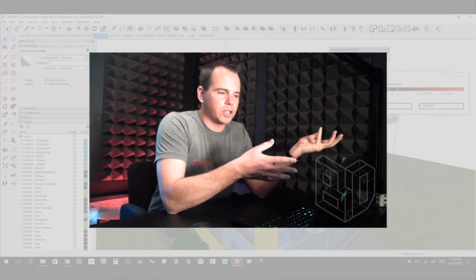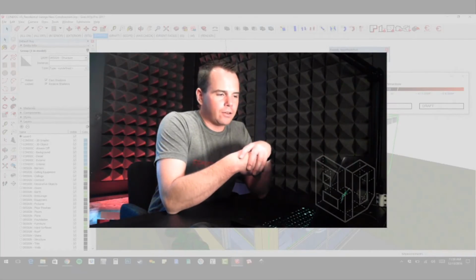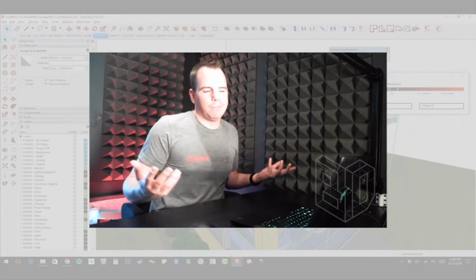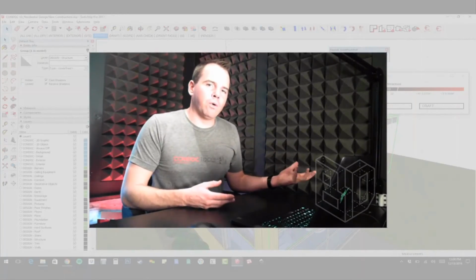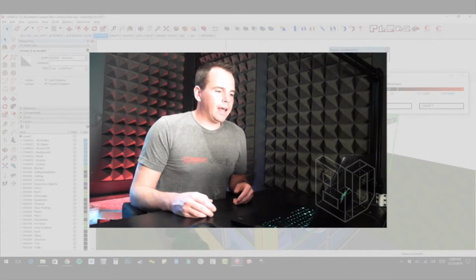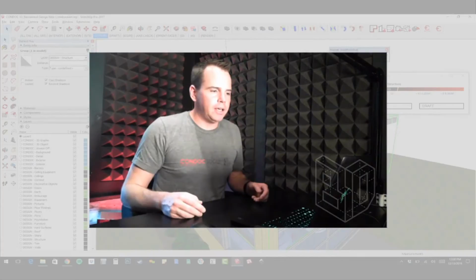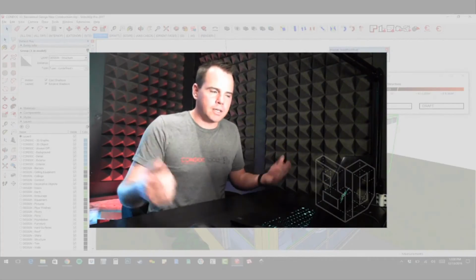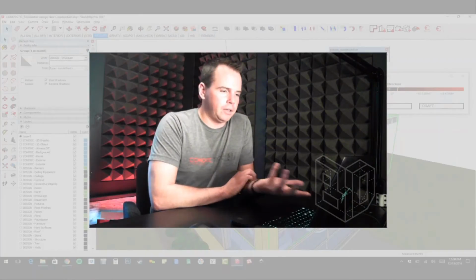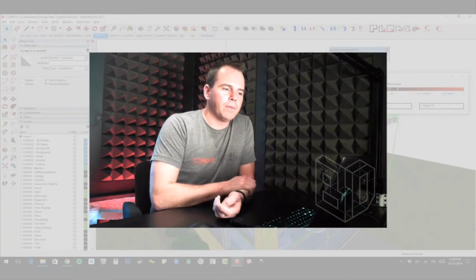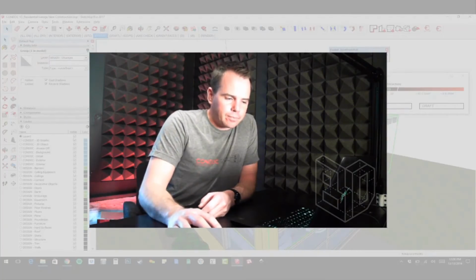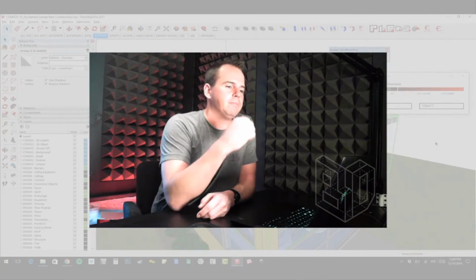I always go structure. So structure is kind of anything that holds the building up. And that could also be 2x4s in your walls. I would put those on the structure layer. It's all the framing, any posts and beams, and everything that goes into the actual structure of the building goes in a group and goes on the layer structure. You would further break this down into levels and all that using the ConDoc system just the same.